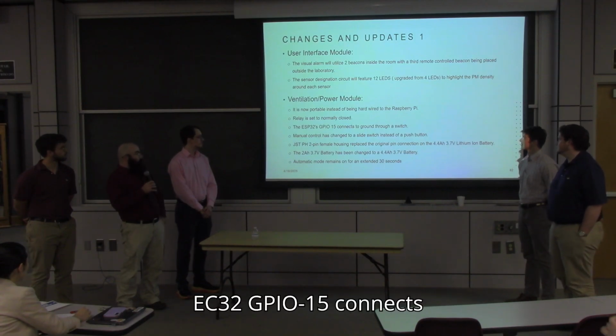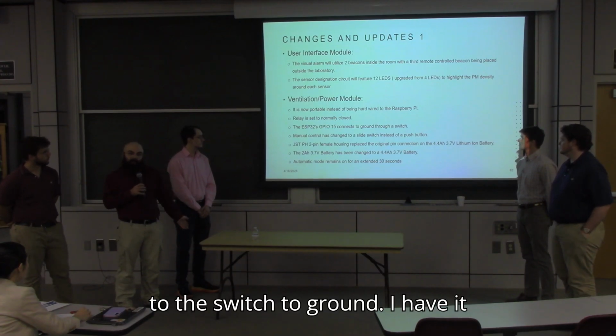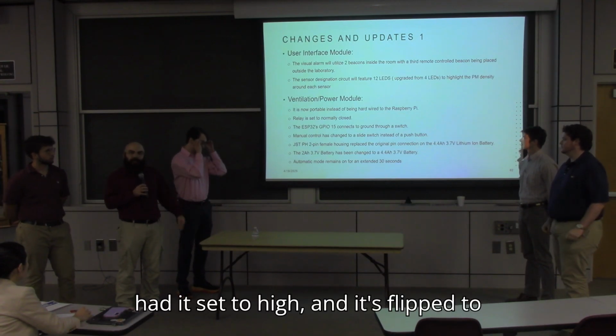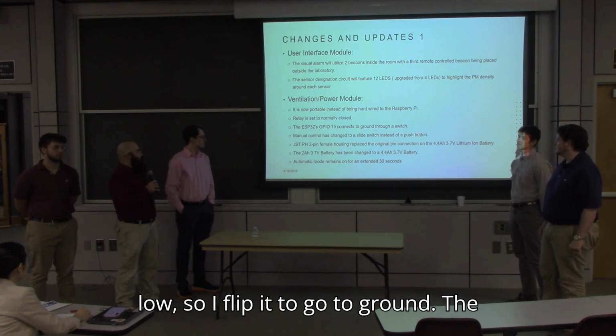The ESP32 GPIO 15 connects to the switch to ground. I had it connect to the other GPIO port, which made the code a little bit too hard, so I just had it set to high and it's looking for low. So I flip it, it goes to ground.